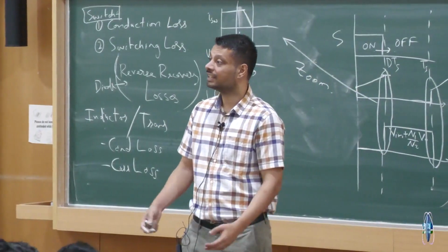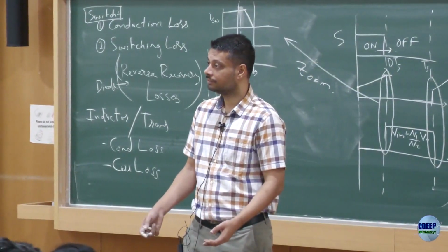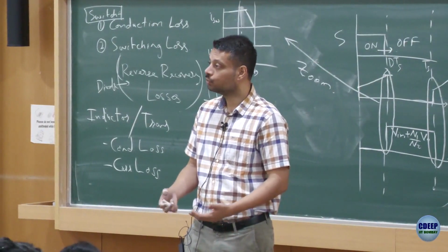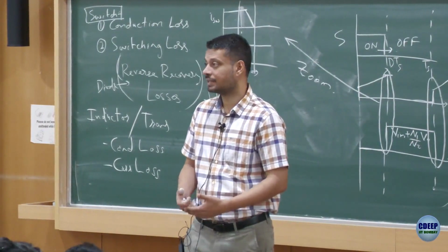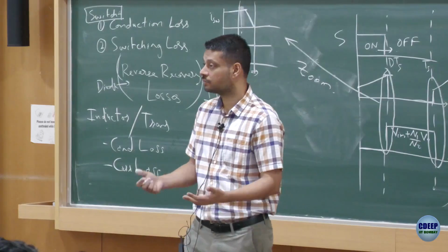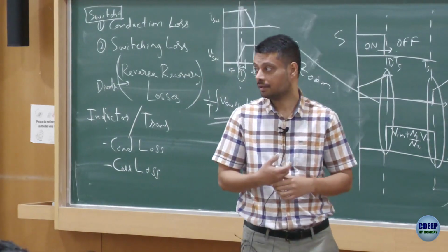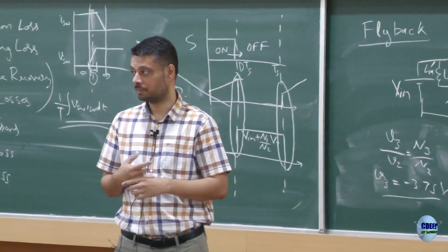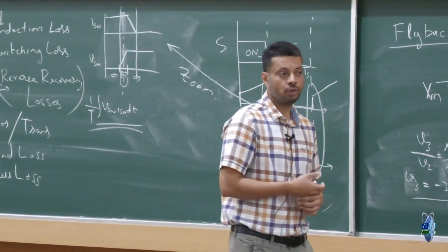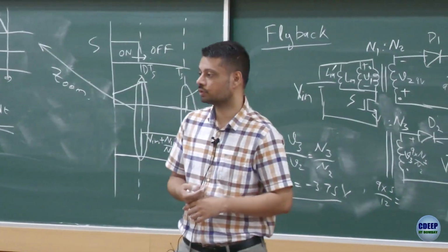Boost will have higher D and that is more desirable. What are you saying? Higher D, boost is not most desirable because as the D increases, your losses become more in fact in a boost converter. This is what we saw. Maybe you are saying the other way around probably. Yeah, so you would not use buck boost, you would use boost, right?